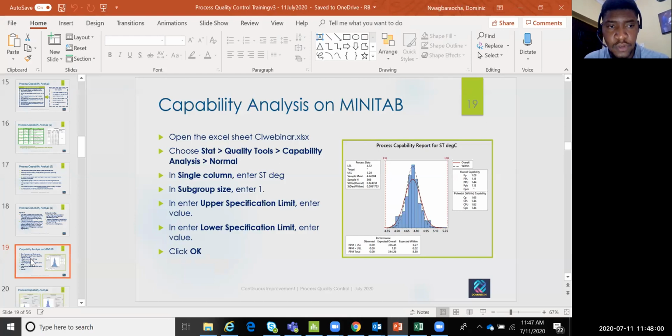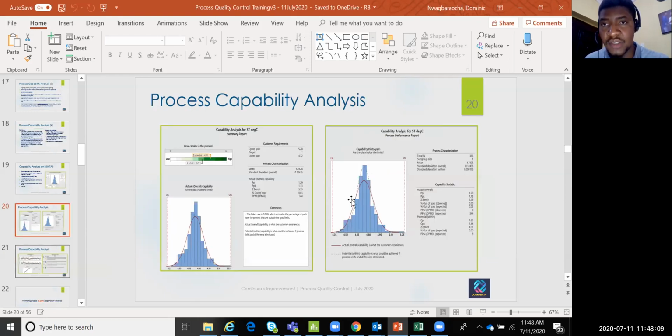Okay, so there's also a graphical analysis that you can do. I would show us this maybe towards the end, so we don't spend too much time, if you really want to understand your process. So I did a capability analysis. I want to know more about this process. I want to know how many parts per million I will be expecting as defects. So in 1 million pieces, you would get 344. That's the number of defects in 1 million.